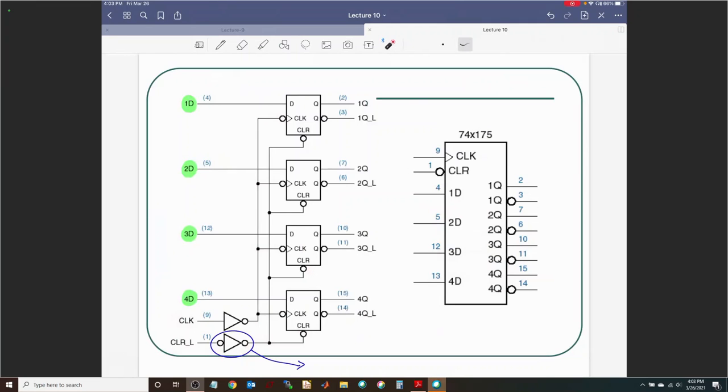So you may have an issue with the fan out, right? So you want to make sure that your logic levels are low enough versus high enough. That's why you have that buffer to get solid logic levels, because already it's connected to four things over here. What if this was connected to another chip with another four things over there?